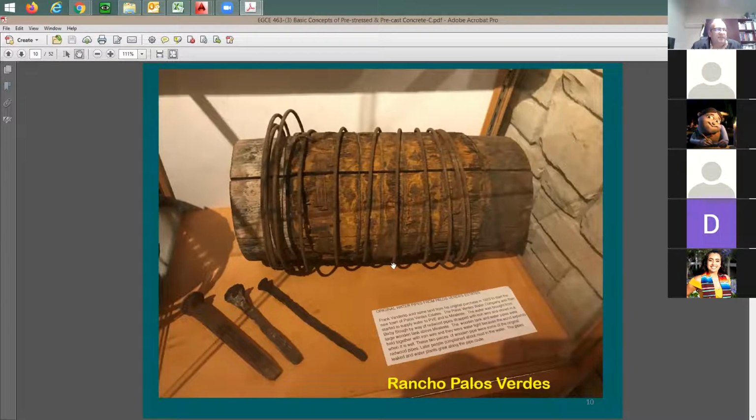And what do they do? They bring this cable or this wire, and then they apply the tension to it. So they really do it very tight. And this is actually pre-stress. Because the stress that you apply here, it is true it's gonna be tension in this wire, in the spiral, but it's gonna be also compression on the wood section itself. So this wood section is like a pipe composed of two pieces, right? It's like two pieces of wood like this. And then once you start to apply the wire around it, you start to pull the wire.